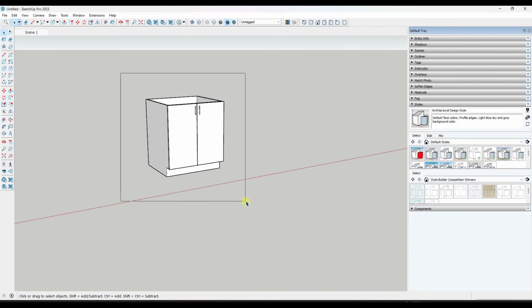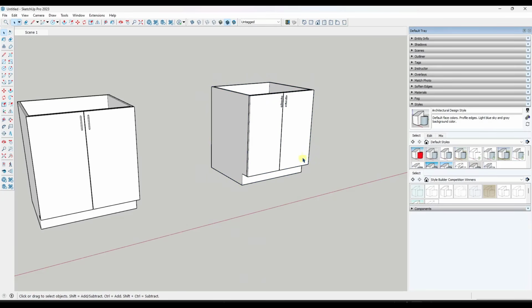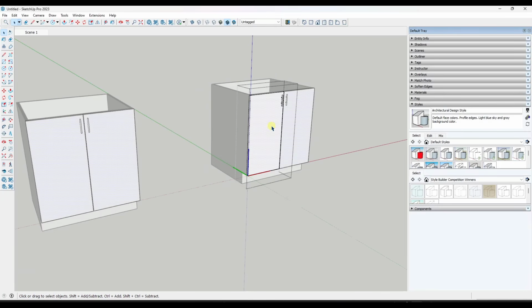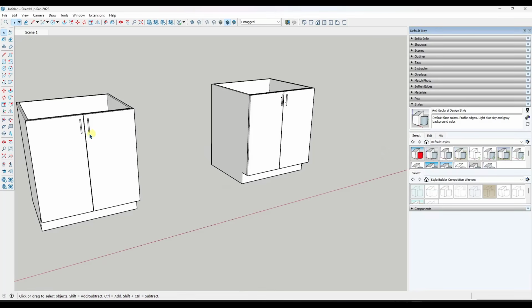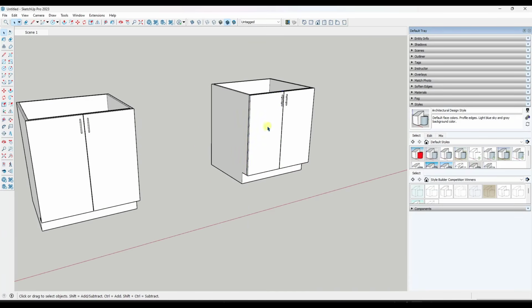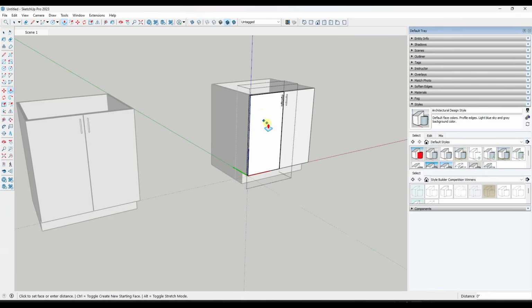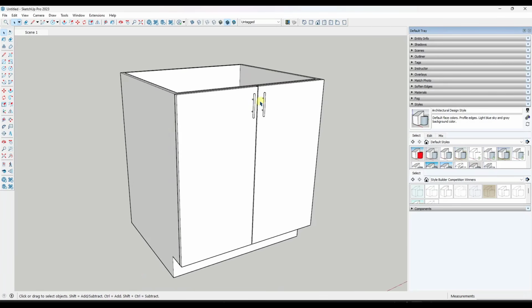And now we've got our simple cabinet with our flush doors. And one thing that you could do is model this with the doors and then create a version where you swap out the hardware. Now, one thing that gets a little bit weird about that is because we're using the same component for these doors and for these doors, if I come in here and delete out the hardware, notice how this hardware is going to go away as well. So what I would want to do is select both of these by doing a click and then a shift click, right click and make them unique, so that now if I edit them, it's only editing the other object but not these, because we made them unique copies.